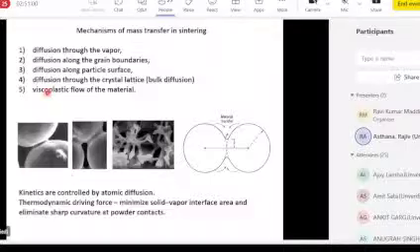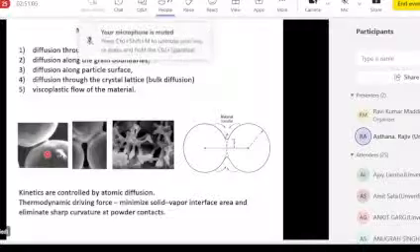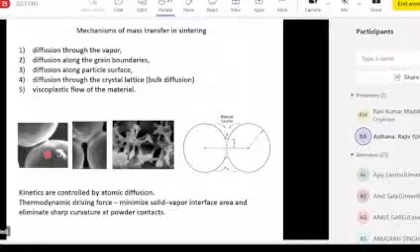And then you also have actual viscoelastic deformation that will cause neck formation. And the problem is that when you sinter multi-phase parts, how do you figure out the sintering temperature? Normally, sintering temperature is based on the largest constituent. So if you have an iron-based material, then you select 2/3 of the absolute melting point of iron as the sintering temperature.